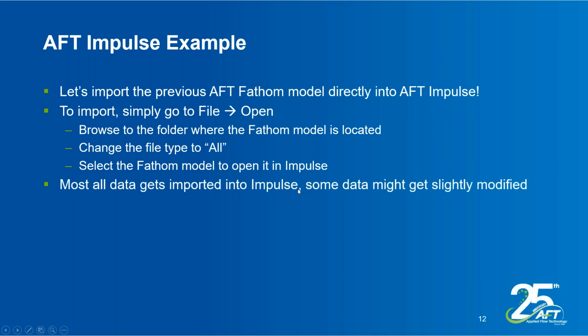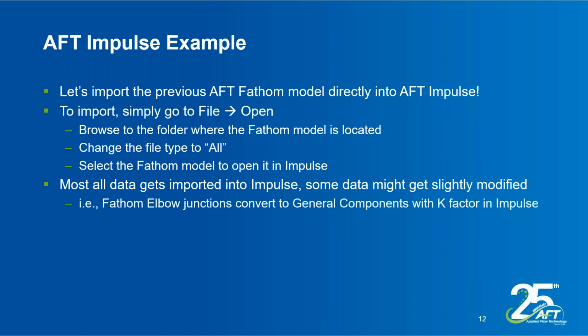Really easy. Mostly all of the data imported into Impulse is really simple. Some data might get slightly modified. An example is elbow junctions convert to general components with a K factor in Impulse.